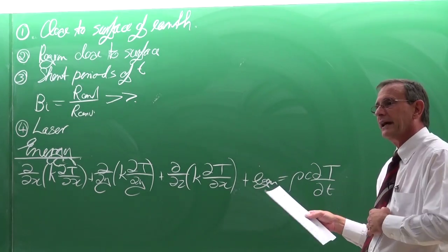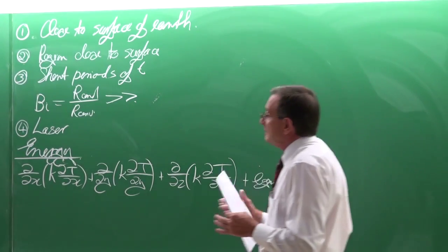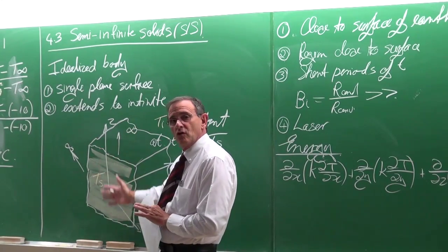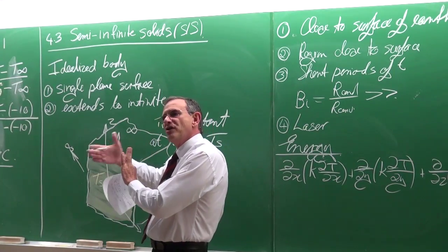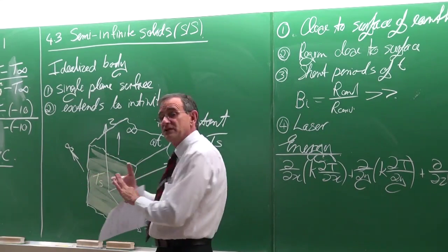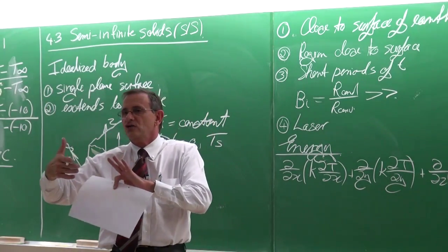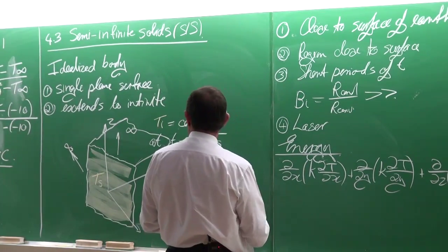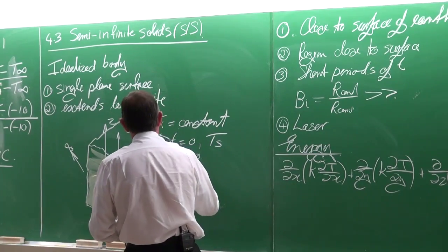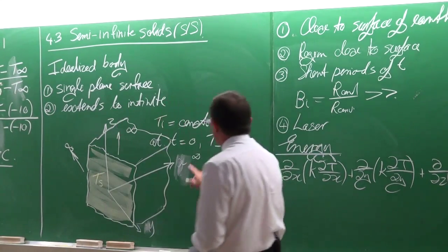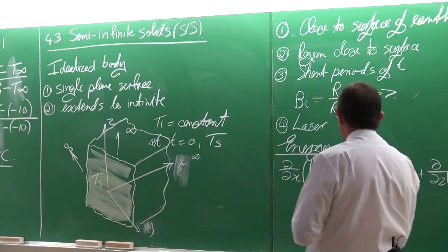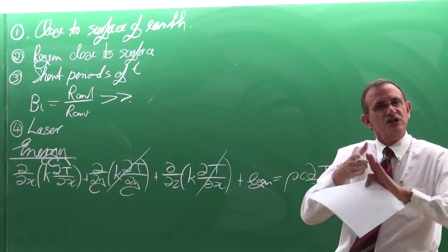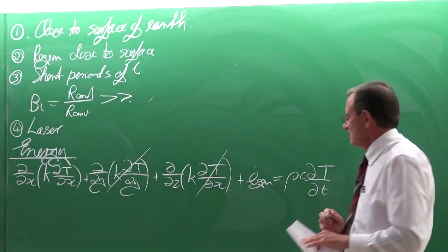Now the heat transfer again. This body is very, very big and we only change the surface of it. Then we are looking at one-dimensional heat transfer, typically maybe in the x direction or the y direction only. So let's suppose it is in the x direction. Okay, maybe my x should have been there rather. So let's change it. It is in the x direction. So it would mean that those two terms are equal to 0. There's no heat transfer in the y and z directions.